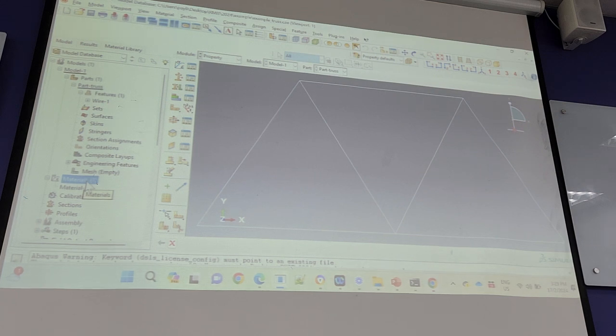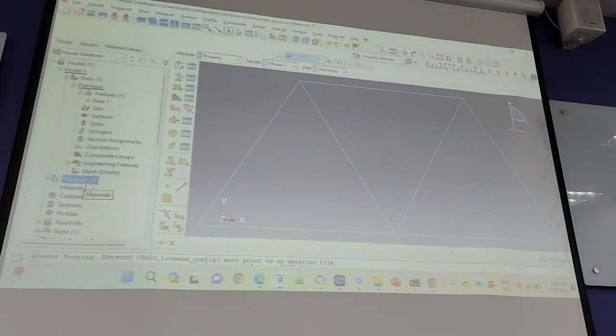Do this line first and assign it to be 1 first. Try a different sequence, it's okay. Or if not, give it an angle, say 60 degrees. After that, come back and delete the 60 degrees. Whatever appears on the screen is the constraint, so how you implement it doesn't matter.